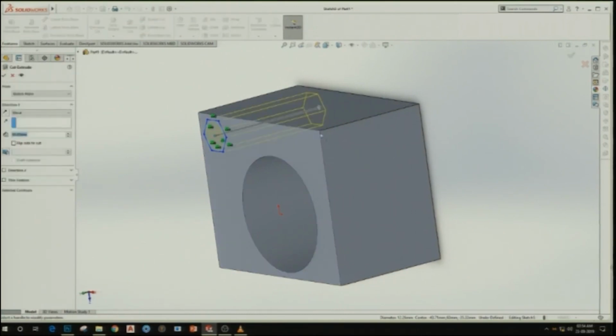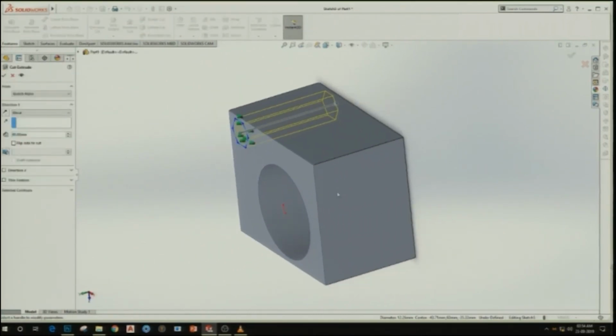We want to apply the same extrusion here. So, it is extrusion cut here. This is already blind. Blind means up to a certain millimeter. Let me try to change its length. Now it is 40 mm blind. Through all would obviously be through all.